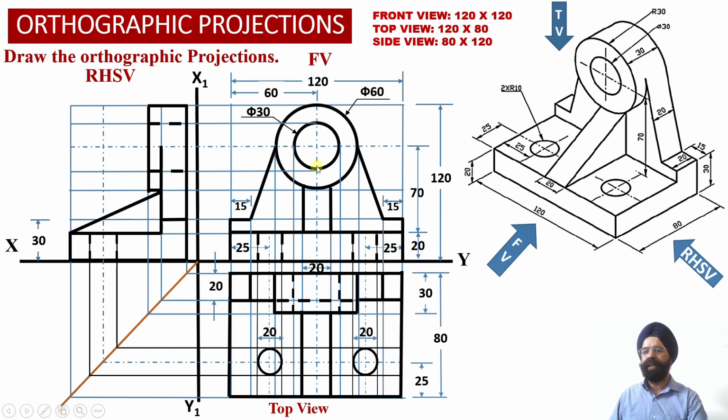And now corresponding to this element, which is a right angle triangular vertical web which happens to be perpendicular to the front face of the solid, this triangular projection we are going to obtain into the profile plane as a true shape, because this triangular surface happens to be parallel to the profile plane over here.